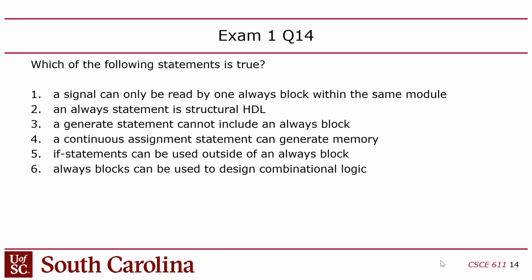An always statement is structural HDL. No, it's behavioral. A generate statement cannot include an always block. No, it can. A continuous assignment statement can generate memory. That one is not true. If statements can be used outside of an always block, not true. Always blocks can be used to design combinational logic, true. So it's number 6, right? 6 is the only true statement.